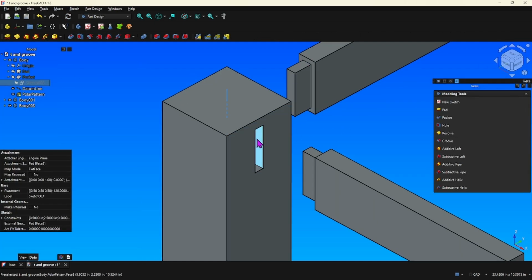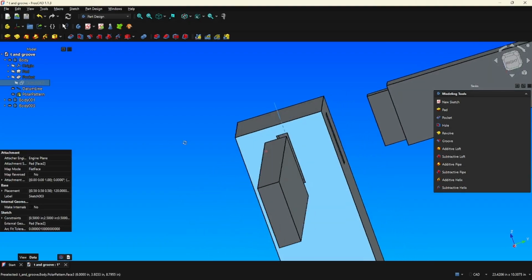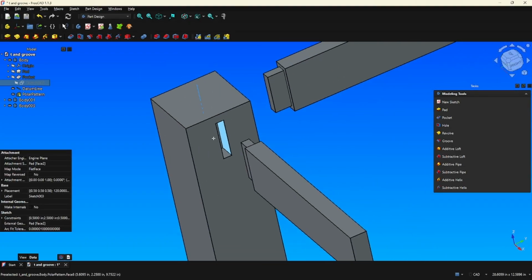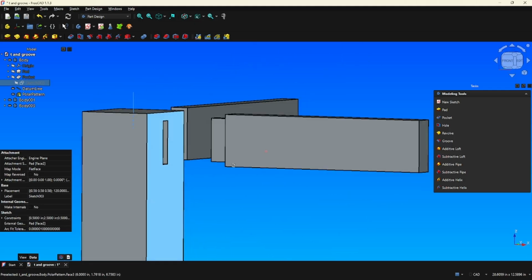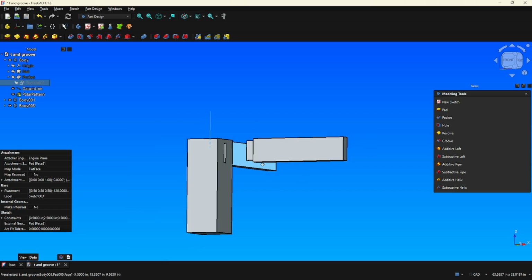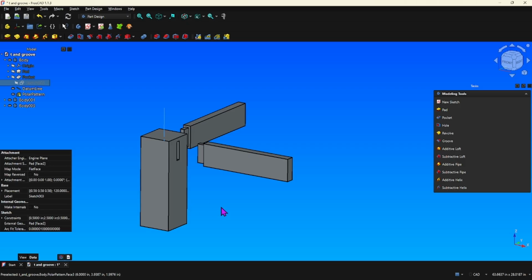Now, because we used the polar pattern and created a second slot on the other face around here, around the corner, that one also dropped down in place. We didn't have to do it twice like he did. All right. So, and he called these the pegs, but these tongues here in this board, we now have to move that down. So we'll have to transform these boards to go down another 1/4 of an inch.